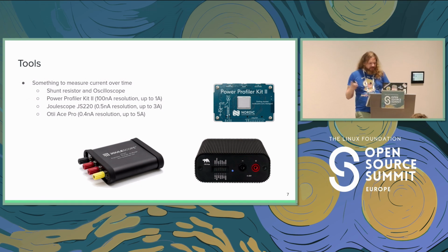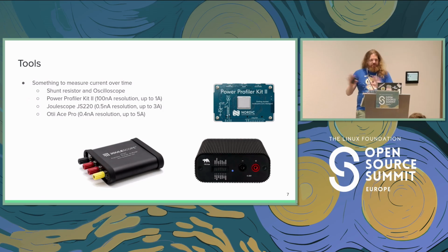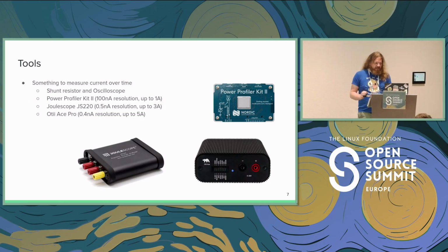I also got a lot of recommendations for the Joulescope, a little bit cheap, about $800 I think, but also really good at that. So get one of these, do some power measurements. All I did here was use the Power Profiler Kit version 2 from Nordic. It does a good enough job.